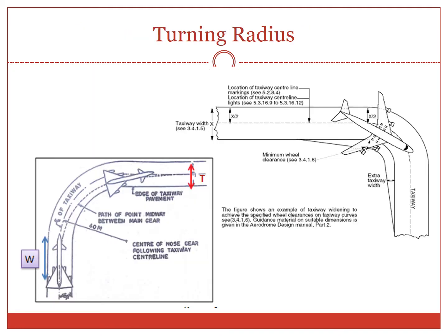Now this figure shows how the aircraft goes from a pavement where a supersonic transport with a wheelbase of 31.2 maneuvers a curve of 60-meter radius. You can see in this figure, for aircraft serving large subsonic jet aircraft, the minimum value of radius of the curvature is 120 meters, whatever may be the speed. This shows you the taxiway radius.